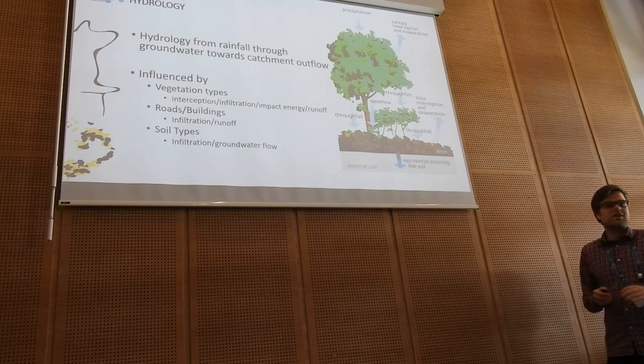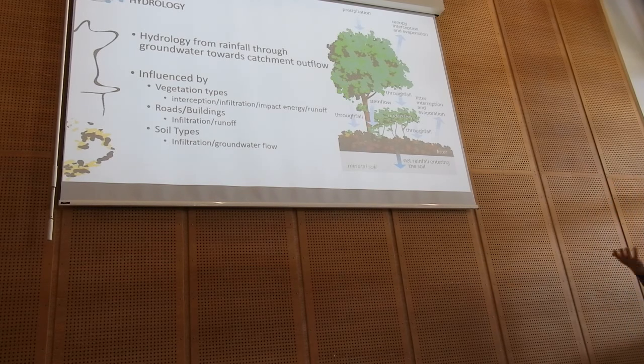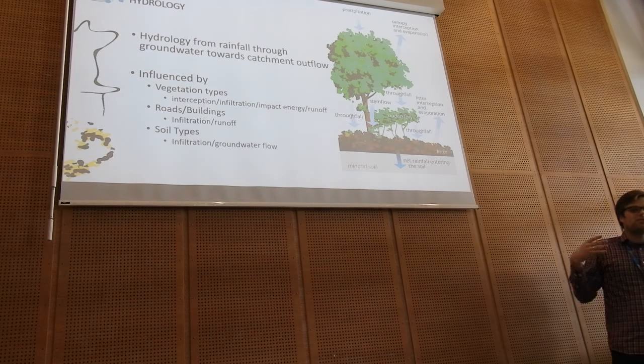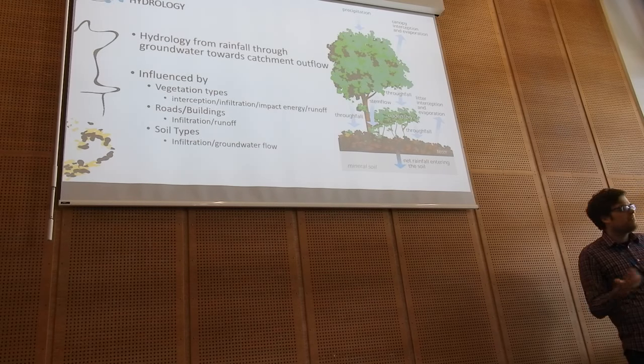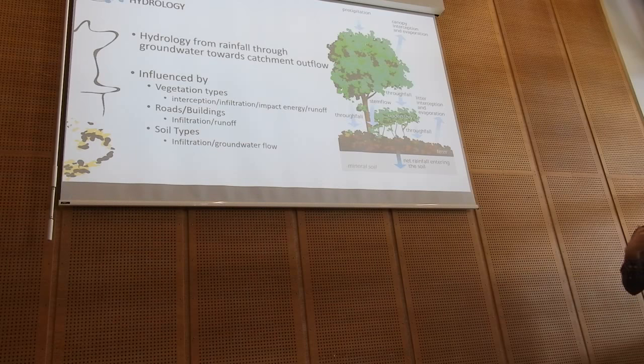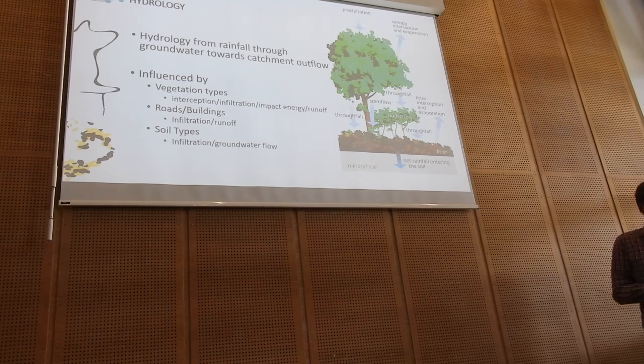Okay, so the hydrology stuff, yeah, same old. It's just similar to others. A hydrological catchment model. OpenLISEM has been doing that since 1993. We include all the stuff from vegetation, so interception, throughflow, splash detachment once the rainfall hits the ground. We have infiltration based on Green-Ampt, and then afterwards groundwater flow is modeled. Hydrology is also influenced by urban elements, houses and buildings.